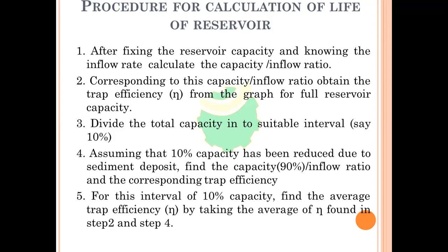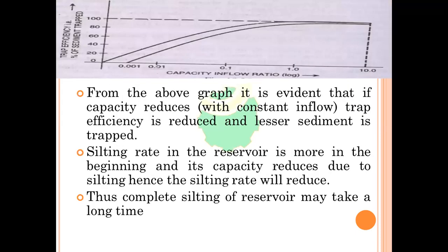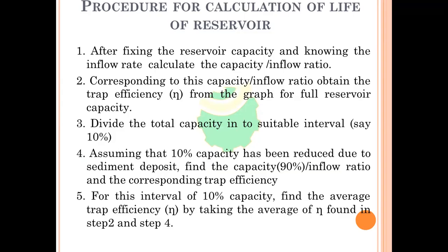After getting the capacity inflow ratio, use the graph to obtain the trap efficiency value. For that capacity inflow ratio of 10, what is the trap efficiency? That value should be taken from the graph.